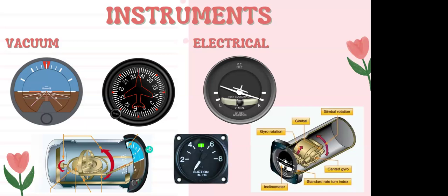And I know I was talking specifically here about the attitude indicator. But it is the same thing with the heading indicator, except the heading indicator doesn't give you pitch. It only gives you roll, essentially. So it's rolling the degrees of the compass. Does that make sense? Are there any questions about the vacuum-driven engine pump or engine-driven vacuum pump?